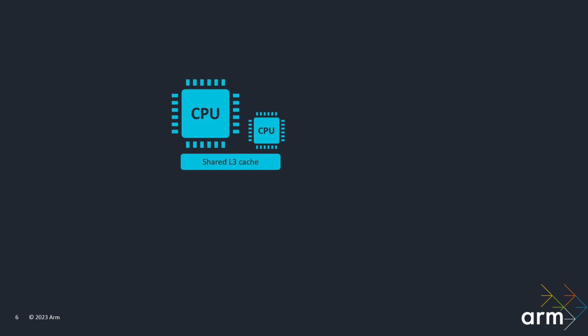What's inside this system-on-a-chip die? Most obviously we have some CPUs. This is going to run the application software, the driver stack, the operating system, and if you've been around smartphones, you'll know there are multiple different sizes of CPU inside these designs. They look like a single set of multi-core CPUs to the operating system, so the OS can choose to schedule threads onto any of these cores. But the reason we do this is to try and find an optimal performance to energy efficiency trade-off.